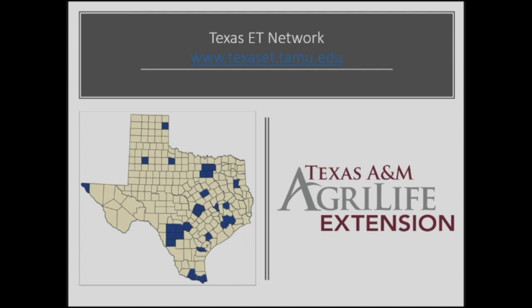And so when we're thinking about how much ET do we replace, we don't need to replace 100% generally, right? Depending on how high quality our fields are. Does anybody want to say, if you irrigate based on ET, how much you replace? 60%? So 60% is the typical for high maintenance, or middle maintenance, I'd say. Yeah. It depends on the use. It depends on the traffic and all of that. So they have some guidelines out there.